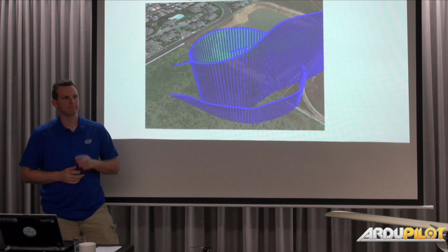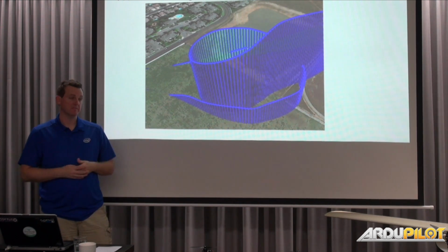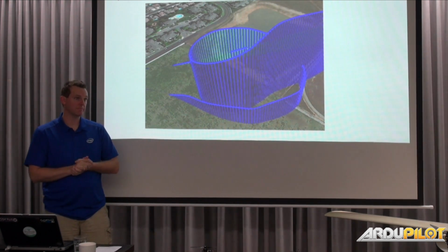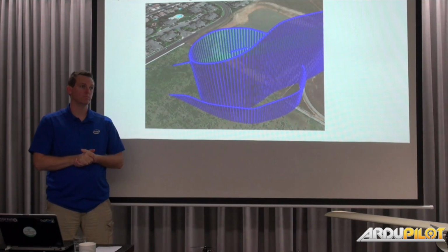Michael, how about if you do the landing and you want to flip the whole plane upside down? Let's say you have an expensive camera payload under the plane, and your winglets, like if you have a delta wing, your winglets are downwards while you're flying. When you're landing, you flip it upside down, so the camera payload and everything expensive is pointing upwards, and you're coming back on your back.